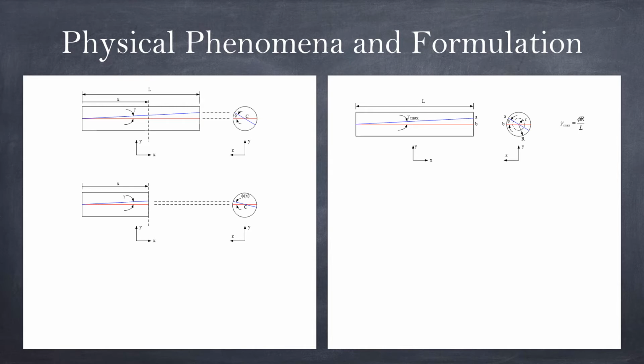Gamma will equal AB over L, and AB on the right-hand side will equal phi times R. Then we take the ratio because AB are equal, and we swap things around. We can have a relationship between gamma and phi as follows, as a ratio of radius and the length. Now, back to where we were discussing that we peel off the outer layer, then we see a thinner one, right?